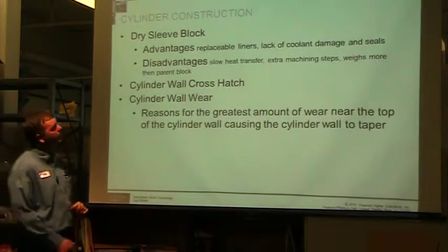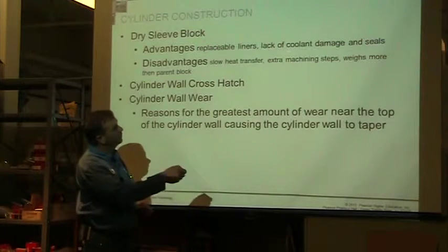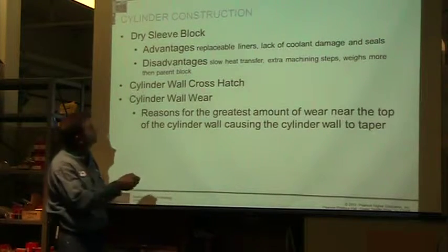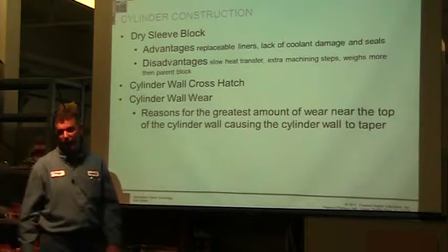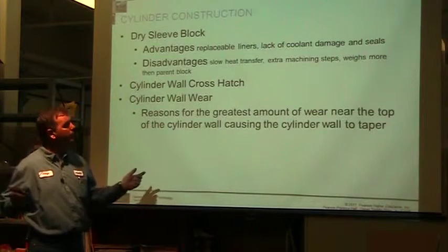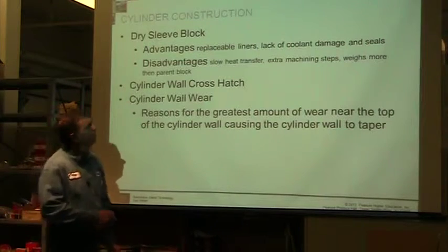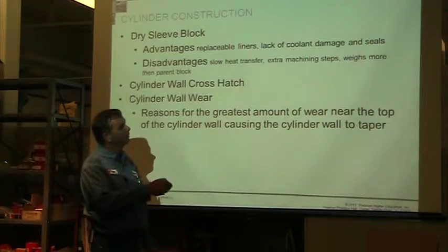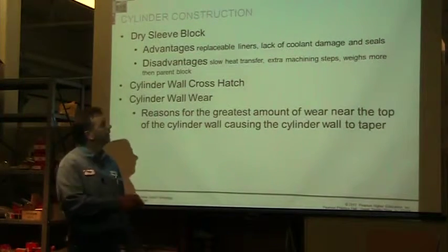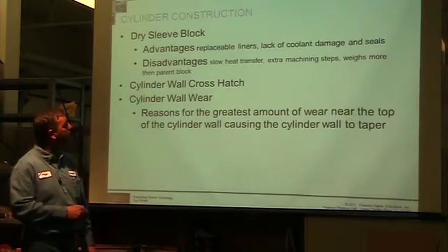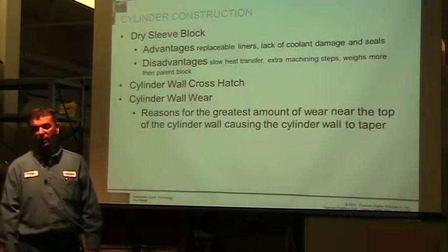The advantage, yes, it's replaceable, and those two items we just talked about are not a concern. Disadvantage, slow heat transfer. We're trying to actually put this coolant or the heat transfer out into the block. It's harder to do that. It takes more time and more steps to machine, and it weighs more than a parent block. So that's a disadvantage.